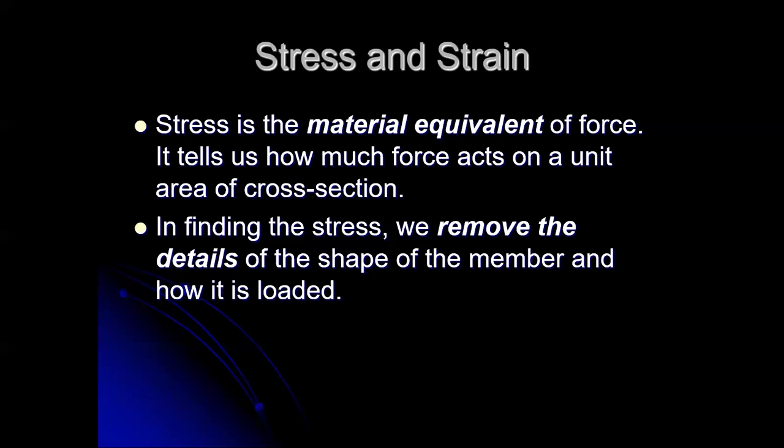We've removed the details of what that shape is. It doesn't matter whether the 10 square inches was rectangular or circular or a triangle. It doesn't make any difference. As long as it added up to 10 square inches, we've got this amount of stress. That's a huge simplification, because think about the world we'd be in if we didn't have it. I'd have to have a big catalog somewhere of every possible shape of a beam made out of a certain material. Let's say aluminum, for example.